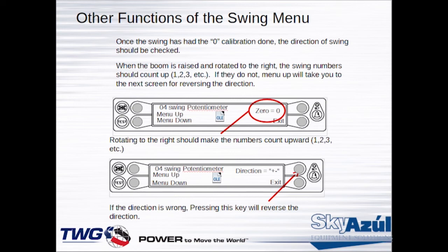Get your tape measure out and check several different points. When I check the calibration, what I like to do is use at least 3 points on the boom extension and 3 angles, and just measure some radiuses and do some compares with the display. And you can allow a half a foot over on radius or plus 10% on the load. If you're out of those tolerances, you need to take a serious look at what's going on there, because there's probably something wrong with your calibration.